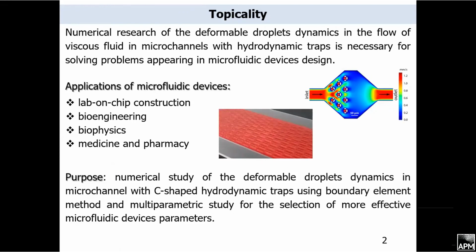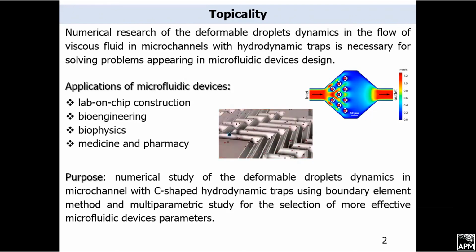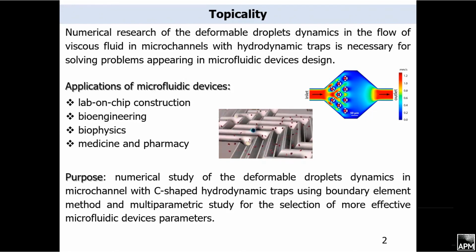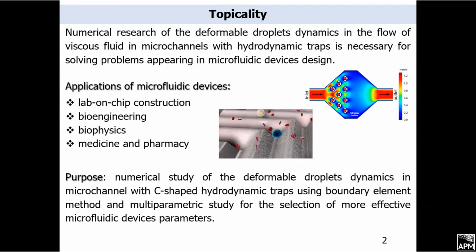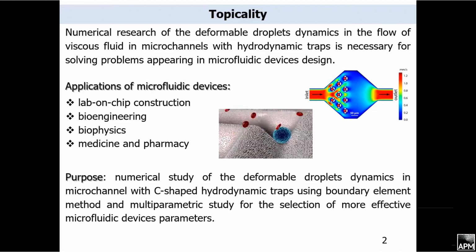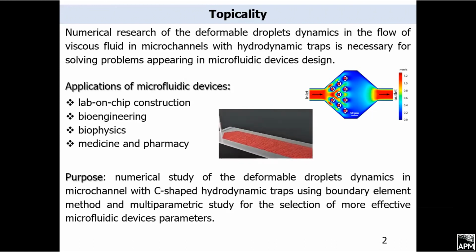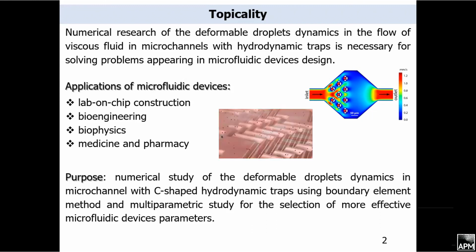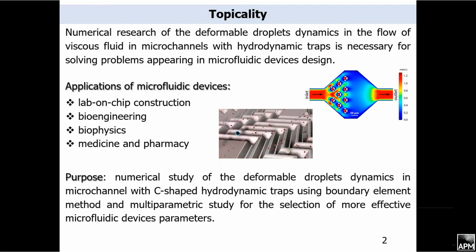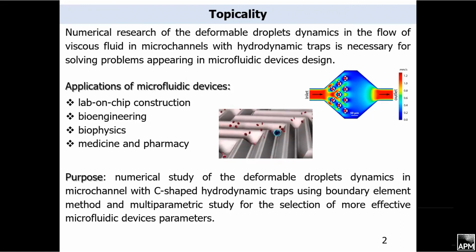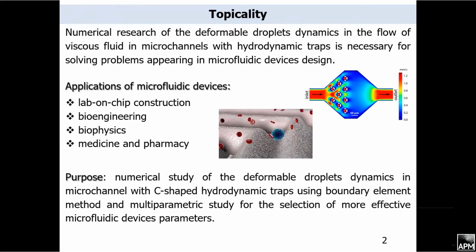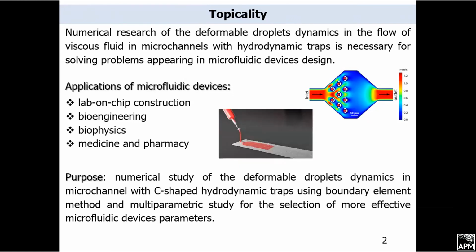3-dimensional simulation of viscous fluid flows in microchannels with hydrodynamic traps is of great importance for microfluidics. Microfluidic devices are widely used in various fields of science and industry. The efficiency of the devices depends on their optimal geometrical parameters. Thus, the primary purpose of my work is to study the dynamics of deformable droplets under flow in a microchannel with hydrodynamic traps and choose the optimal trap configurations for droplet fixation using the accelerated boundary element method.